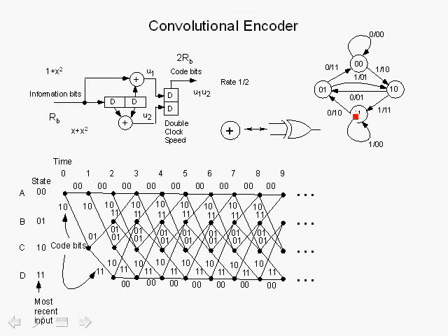And if we enter, for example, a 0, then of course the 1 would get shifted out, and we get a 0 moving in. We go to the state 0, 1, and if we enter another 0, obviously we go back to state 0. In the case where we're in state 1, 1, as long as we receive 1s, we'll stay in that state. That's shown over here.